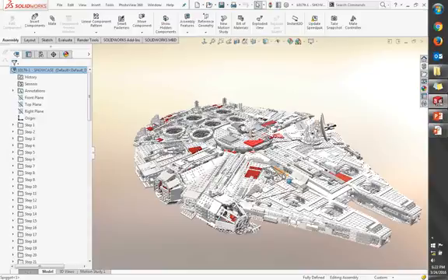So everything is mated fully in here. I didn't use that fixed constraint that we have, that fixed so it doesn't rotate or stop rotation mate. So I literally showed you how I put the parts together earlier. That's the same methodology I used here as well. So everything's mated together. And then as I was going through, I realized, oh, you know what? If I fix a component, the mates for that component get locked out. And I'm like, okay, so that's kind of cool.